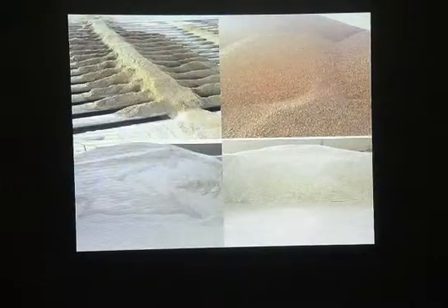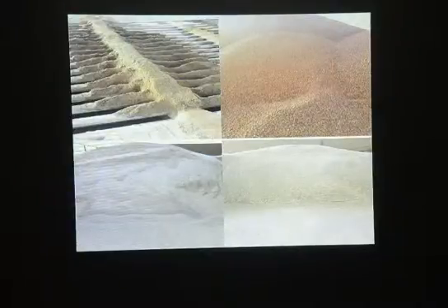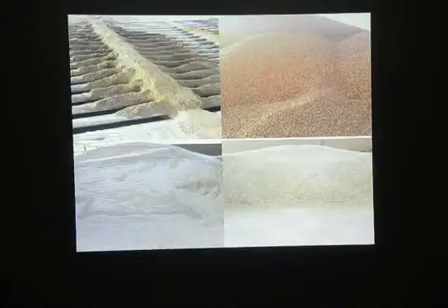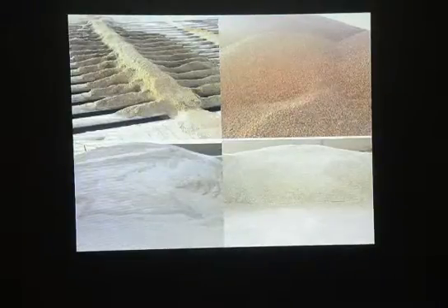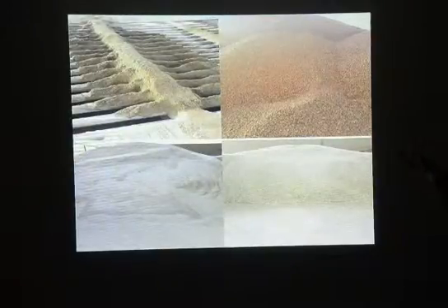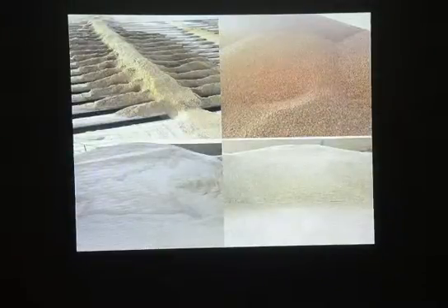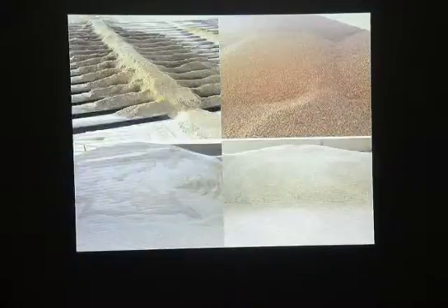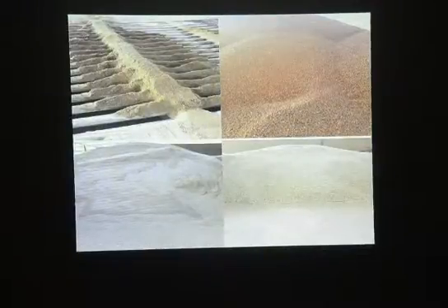That's why we mentioned earlier about normal weight. Normal weight block is the heaviest block that's available. There's no heavy block. It's normal weight. That's why the density is higher, 135 pounds per cubic foot or higher. It's the heaviest weight that's available because the aggregate is larger.